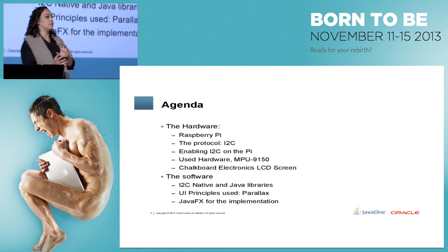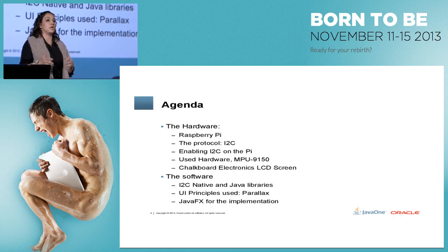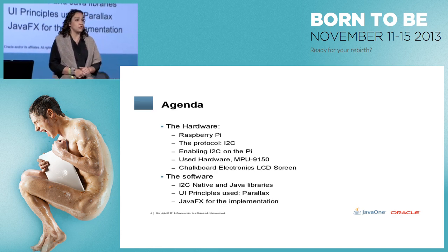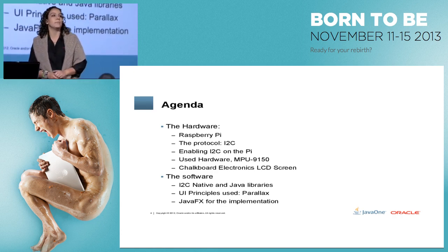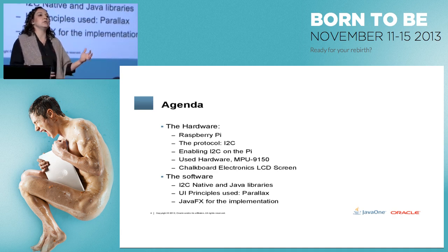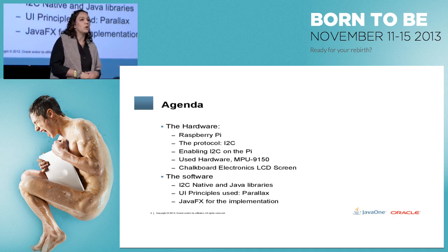So the drawback of using Java SE Embedded today is that I didn't have those nice APIs for accessing those devices. For working with I2C, I needed a solution. Fortunately, there is a very nice library called Pi4J that allows you to connect peripherals in a very easy way. So that's what I ended up using. I ended up using Java SE with this particular library, and things worked pretty well. And then I used JavaFX for the interface.